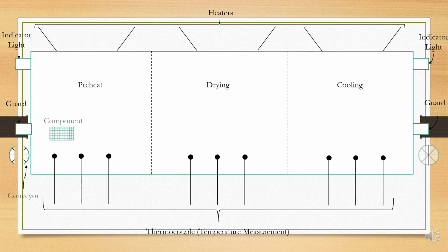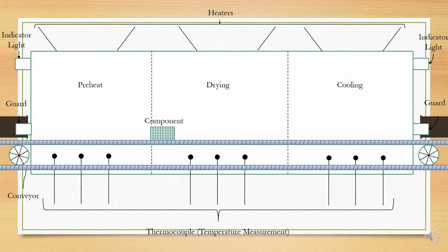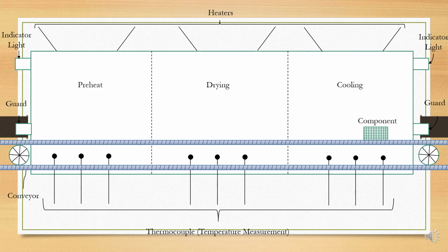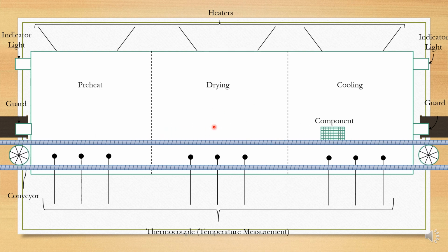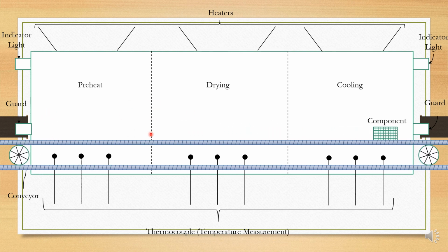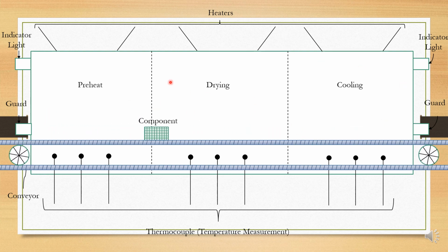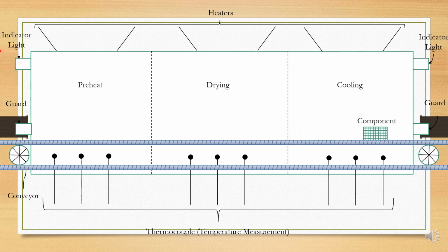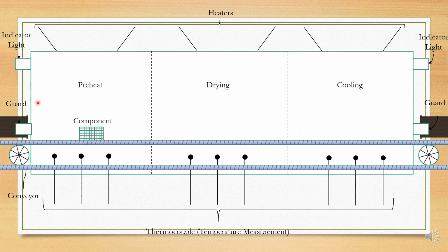One more important functionality is the temperature monitoring of the drying oven. The temperature at each heater area is read every 2 seconds. If the temperature in a heater area varies by more than 5%, the alarm signals have to be asserted.